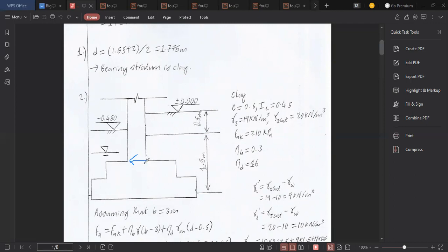So you multiply it by what you assume is the distance of your foundation, from here to here. We just assume, we don't yet know. We're going to assume for the meantime and find out if it's correct. What Faith assumed, and what I've also followed, is that this thing is about 800 millimeters. So that's what she's using in her calculation here.